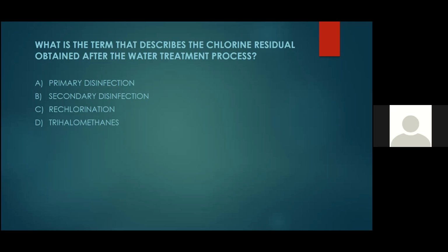So knowing that primary kills the bugs and secondary leaves you with that protection out there, or that residual. And that's the word you're going to look for in your test, residual. And that tells you that's secondary disinfection.